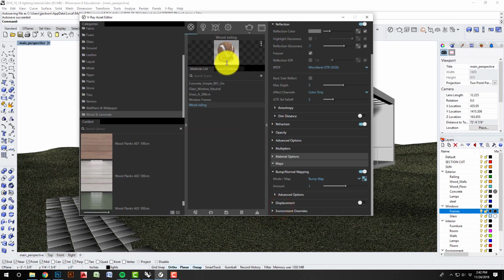We'll go back, and this is where the Vray preview fails. You're not going to be able to see it that well, even if we do this wall close-up version. There are a few different options for how you look at what you're creating. You're not going to totally see it, but this is where experience comes in on getting your settings just right. So 1 is always a good place to start for the texture. I think it might be a little strong on this, but let's just render it at 1 for the amount here.